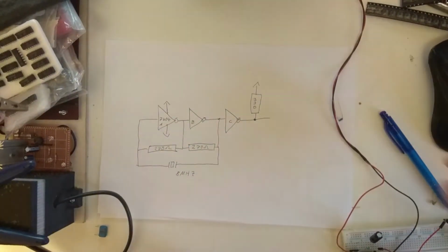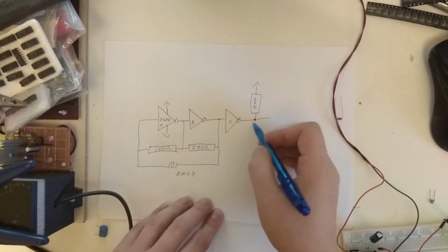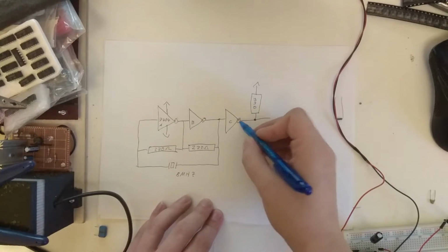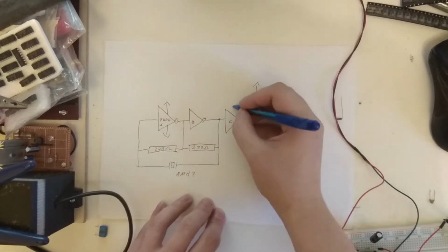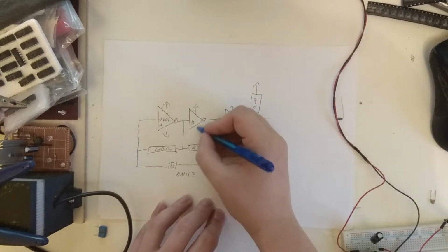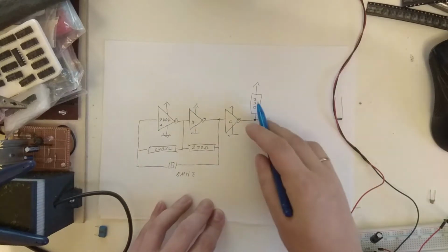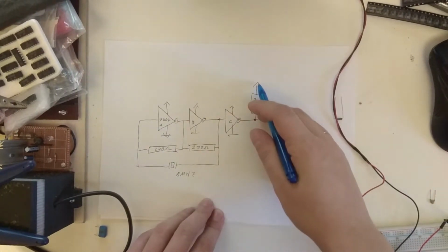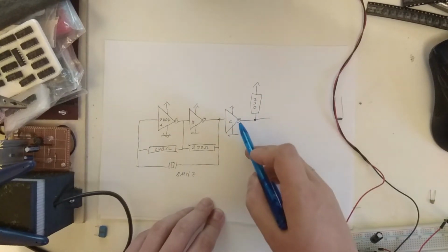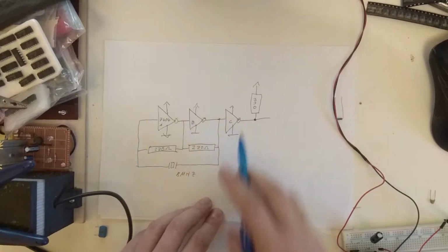So I thought about this, and the only thing I can think of is that this TTL gate won't actually go up to exactly 5 volts, the supply rail. Here, yeah, it's on all of them, like this. So this actually will probably allow some current to flow down here and actually pop it up to 5 volts, although I'm not sure about this.